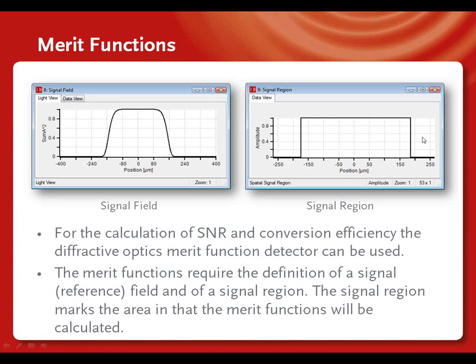So this is something you cannot do if you optimize such a beam shaping element by ray tracing, because in ray tracing you don't have stray light or you have no measure for it. But in VirtualLab it is possible, because we include diffraction and interference effects, and this means automatically that you can also use some stray light, or that you can scatter light to higher angles by introducing high frequency modulations of this cylindrical interface, and so increase the quality of your laser line.